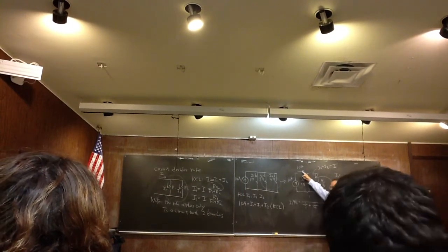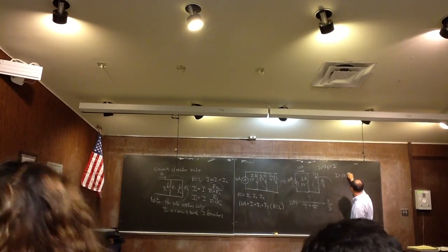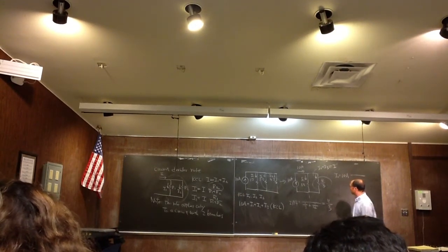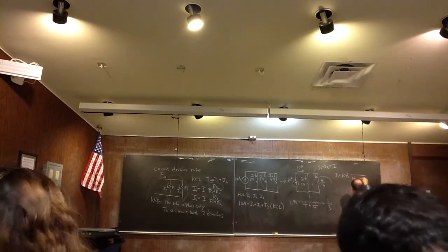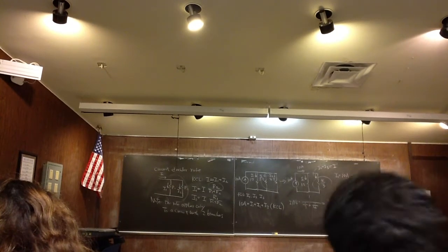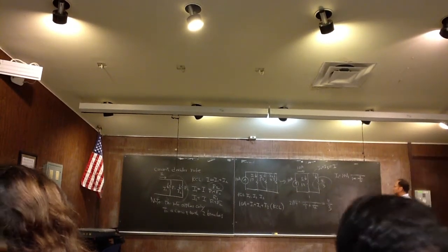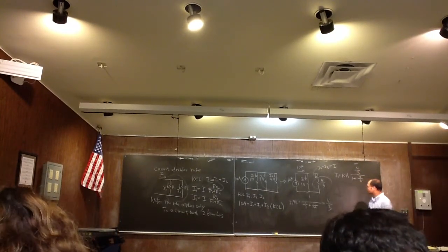This current must be smaller than that, right? Okay. So I1 is equal to 10 amp times, according to the current divider rule, the sum of the 2, 1 plus 4/3, and then the top one is 4/3, right?